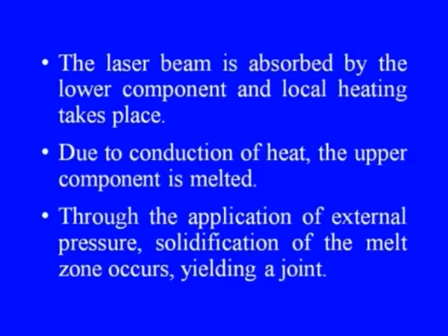The laser beam is absorbed by the lower component and local heating takes place. Due to conduction of heat, the upper component is melted. Through the application of external pressure, solidification of the melt zone occurs, yielding a joint. In brief, in this laser welding process, we have studied the process and the features of laser beam welding, laser applications and new trends in this category.